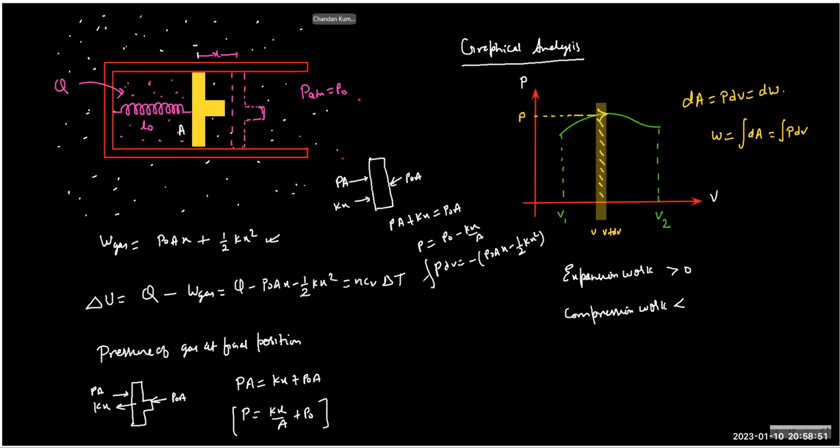So you can see that the work done by the gas we have to take here is negative, and this is the work done. And negative means you're receiving the energy. Anyway, if this is the work done by the gas, then if you apply the formula Q equals work plus delta U, it will go this side. And what we wrote in the very beginning, the same answer we're getting here, isn't it?